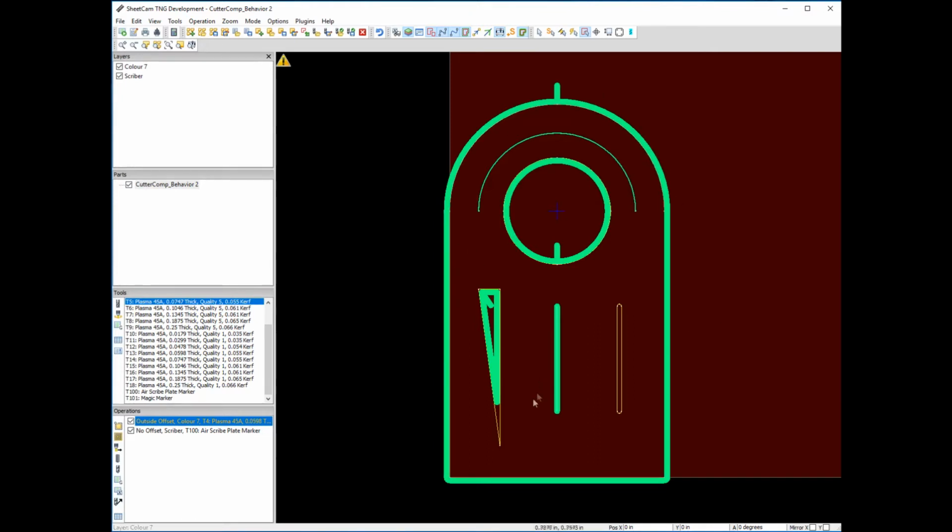Now, let's say you cut this part out, and let's look at this triangular slot here, and you measured it from here to here, and it's a larger distance. You expected the distance from here to here. Here's what happened. As she was coming down the kerf with the torch, it necked down to where that 55 thou kerf width can no longer fit into this area, so it just went back up the other path. That is the problem right there.